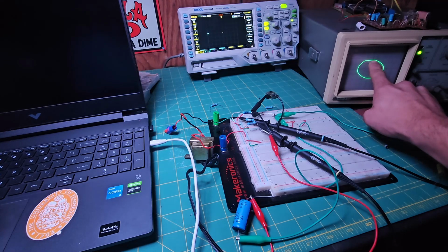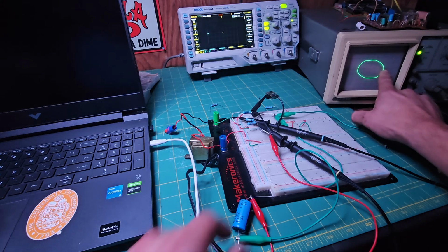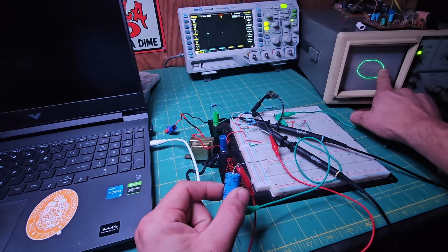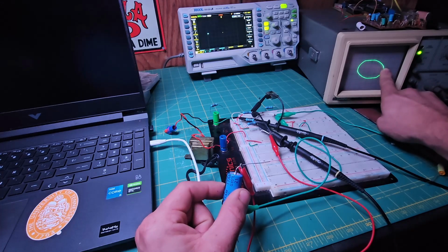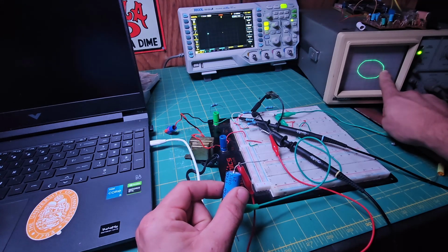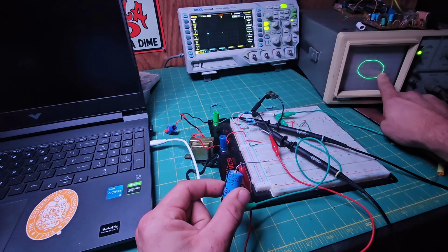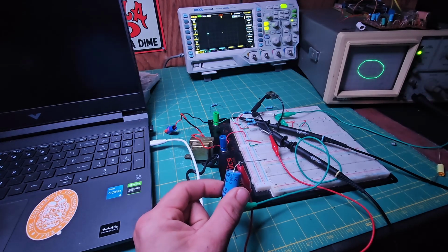But then, as the voltage is rising this way, it begins changing less and less. And eventually, when you reach the point of the peak, there is 0 current being flowed into this capacitor. At which point, once we hit the 0 point here, this is when the polarity reverses. And so the electrons are moving the opposite direction, and therefore the current is as well. We get a discharge. So this would be like a discharge cycle on that capacitor. It is now providing current to the circuit, and the amount to which it can do that is dictated by that same equation.